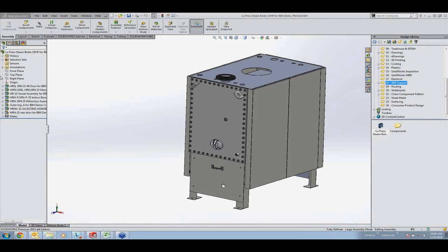Another option here is between a rectangular member and a round member. I don't see a preview yet because I need to assign a direction. So if I assign the horizontal direction, see the preview here. That's not what I want, so I'll change that to a vertical, and now that is exactly what I want. Go ahead and unpin and accept. All right, looks great.